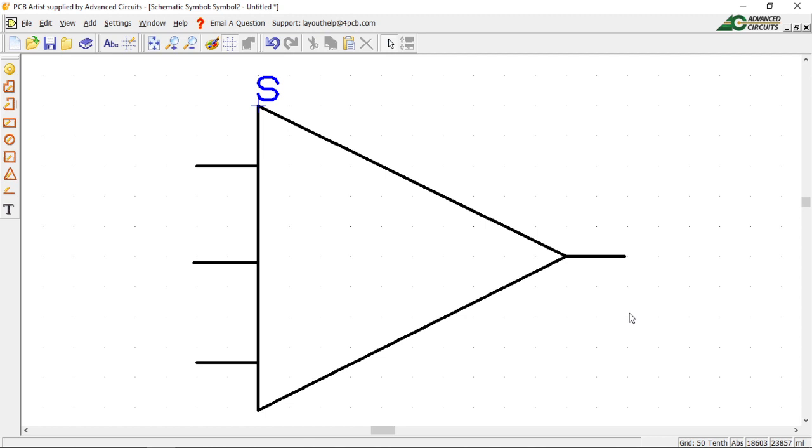And so we're going to add some pins. The way we add pins is click on this. Now notice that when you add pins, it's going to start at 1, 2, 3, 4, and 5. Or actually it'd be 4 here. So when you're doing this, kind of remember how you're doing this, and if you got a different shape, you might want to start clicking first on the pin that you want to be pin 1.